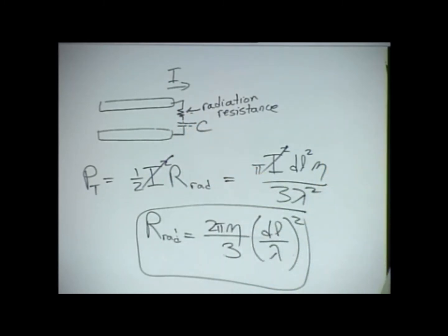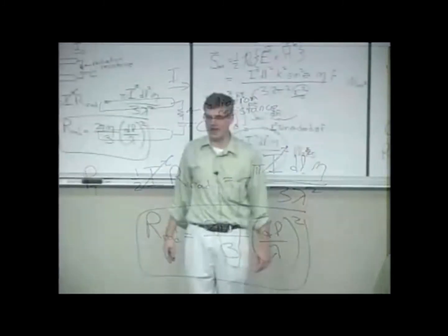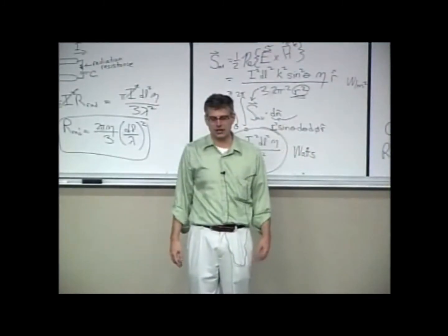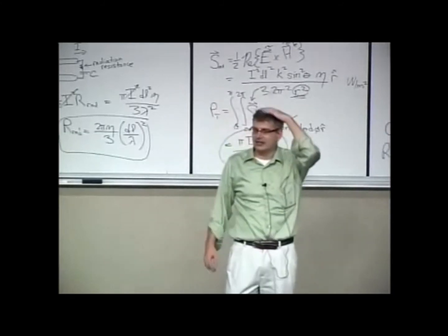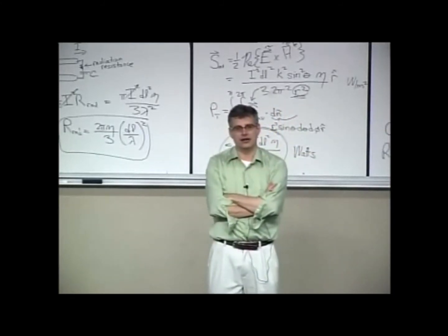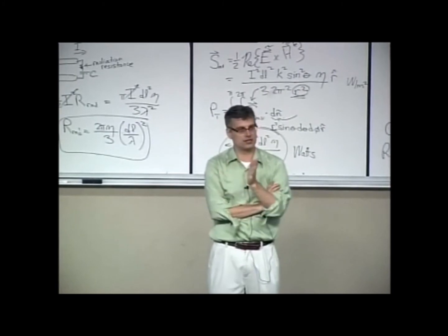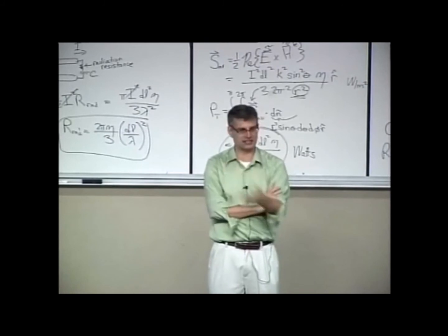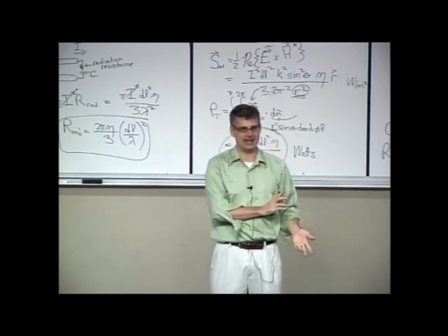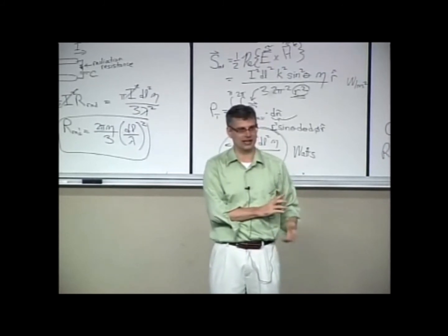And so there's only so much I can do to get rid of that capacitance. And that's just one of the many travails of matching these types of antennas. So you'll find the only place that I can use electrically small antennas is in the field of, say, low-frequency communications, where my free space path loss is so low anyway, I can take lots of lumps in my antenna losses and still do communications.